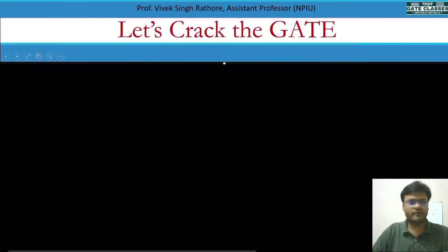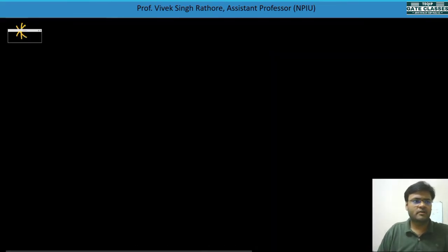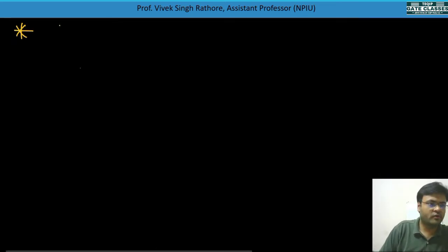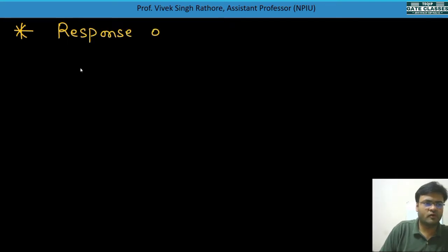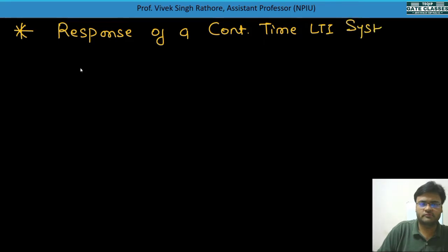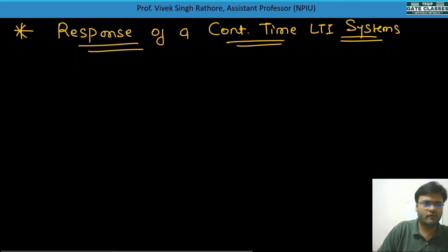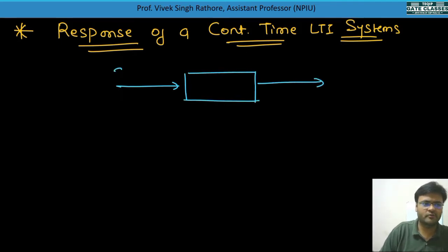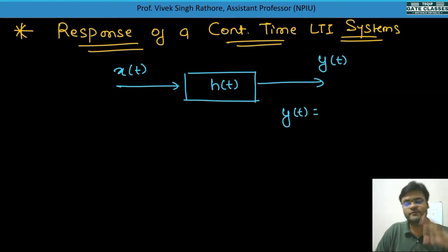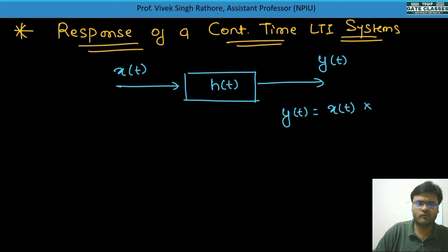So let's get started. We'll write the topic here: response of continuous time LTI systems. What we want to see here is that we are giving an input to a system and we are taking the output. Let's suppose your input is x(t), the impulse response of your system is h(t), and you are getting output y(t). As we have seen with x[n], h[n] and y[n], we will take convolution. So we get the output response as the input convolved with your impulse response.